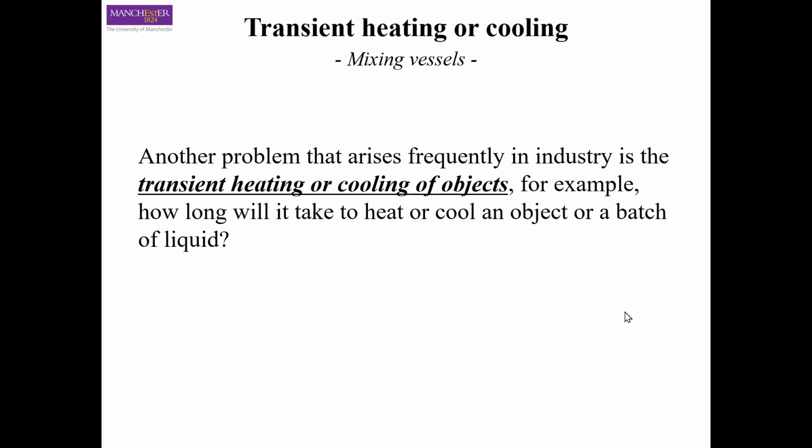But also in a lot of other applications, for example in pharmaceutical or in niche chemical applications, we use another kind of reactor that is called a batch reactor. It means that we don't have continuous inlet and outlet flow from the system, but we just make the system or cook the system in a batch. We want to know that when we start heating, how long it will take for the desired temperature to be achieved. This phase of change in temperature over time is what we call the transient heating or cooling process. So this is very important in chemical engineering in many different applications.